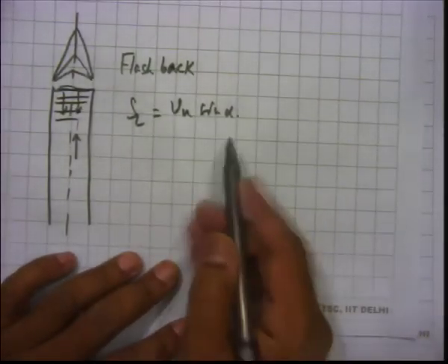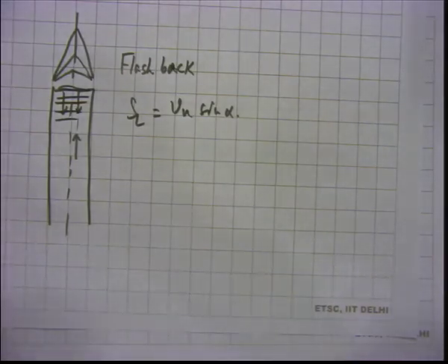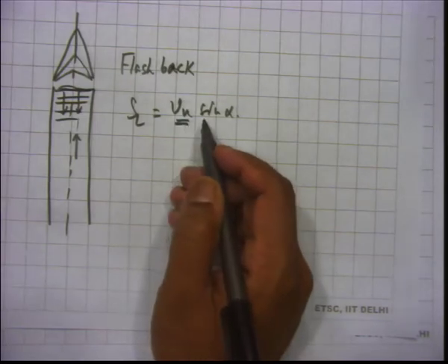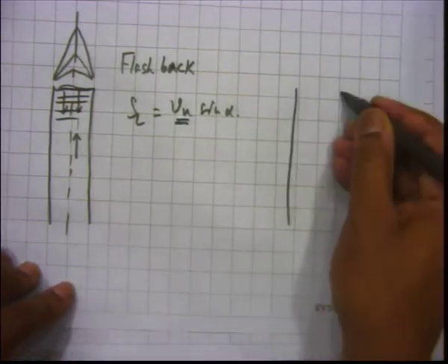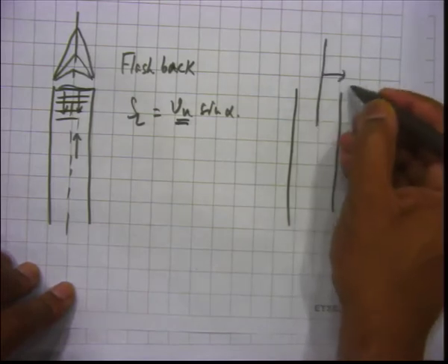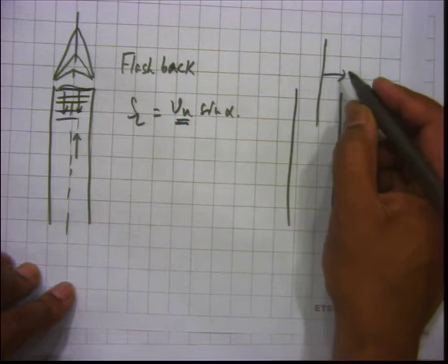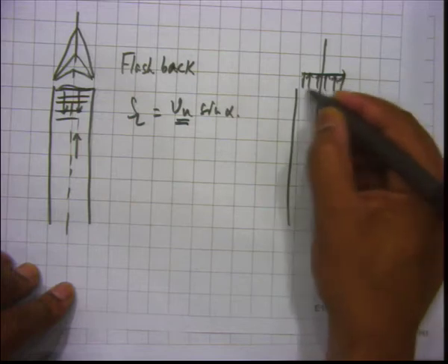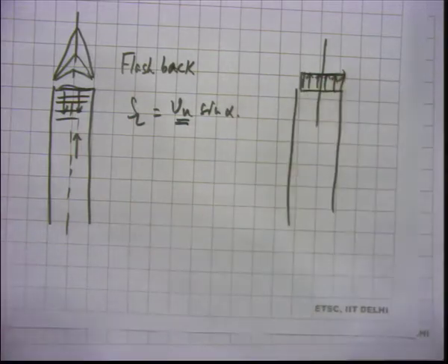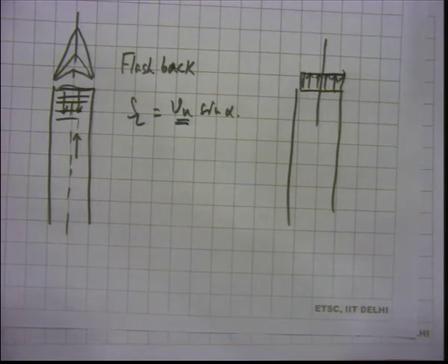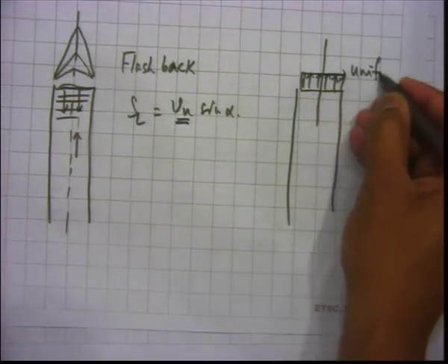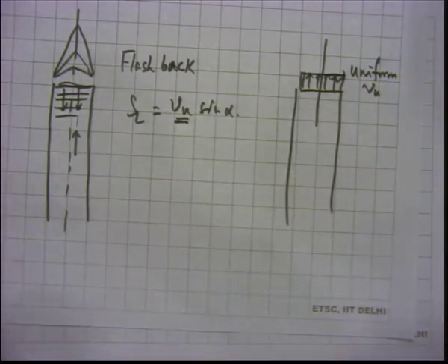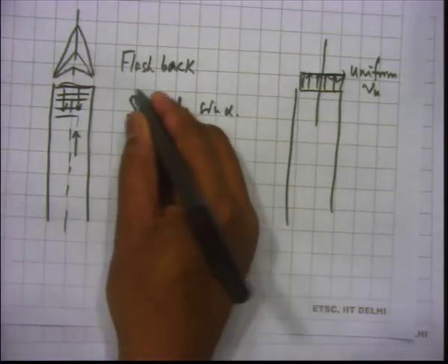But broadly this is the situation, and we should also focus a little on how exactly this happens. Remember, in the last lecture, lecture 26, I said that if this Vu is uniform, that is, on the top of the burner, if you move radially, Vu does not change. Suppose you have a flat kind of profile, that is uniform Vu. Then you will get a sharp cone. This is what we discussed last time, because SL is typically one number.